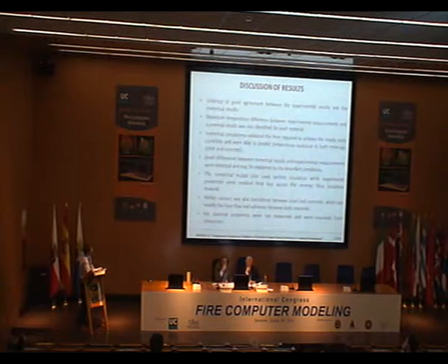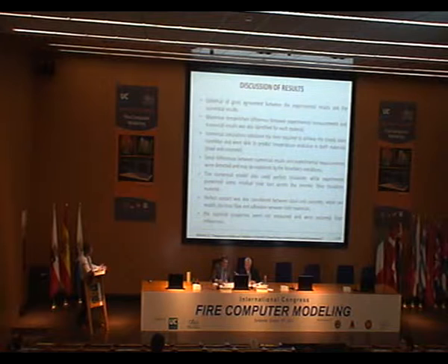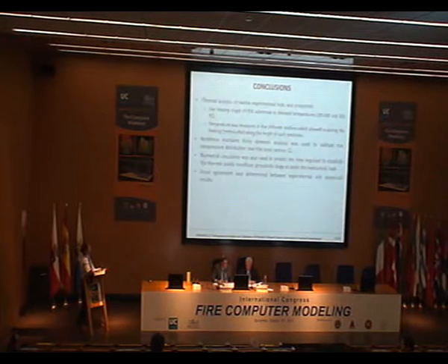The numerical model also used perfect insulation, while the experiments present some residual heat loss across the ceramic fiber insulation material. We decided to use perfect contact, which can modify the heat flow between steel and concrete. And of course, the material properties were not measured, so we assumed them from our references.